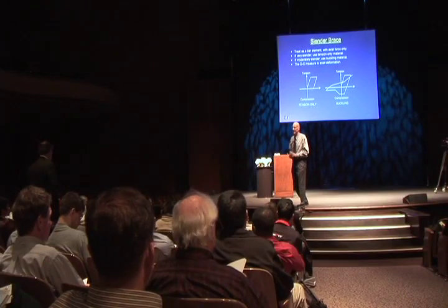And also, there are some cases where you introduce lateral resisting elements at various floors, and you may want to look at a link element in your diaphragm. Is it possible to look at that with Perform? Perhaps a link element in your diaphragm where you introduce more stiffness at a lower floor if you have setbacks in your building.